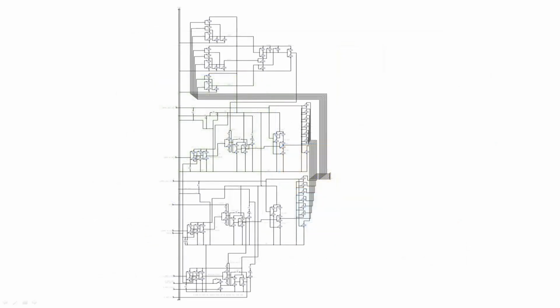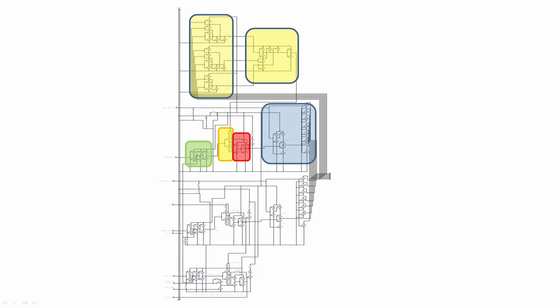This is the whole status register. At the top you've got the OR gates coming in, feeding into the AND gates of the 0 flag. That's the 0 flag control circuit coming in, and that's the 0 flag memory cell. And that's the control AND gate for the pulse signal. And that all feeds out here. On the right you can see the 7 transistors that pull D0 and D2 to D7 down to 0, and then the output goes out of D1 to give you either a 0 out or a 2. And it goes out to the data bus, which is on the right there.